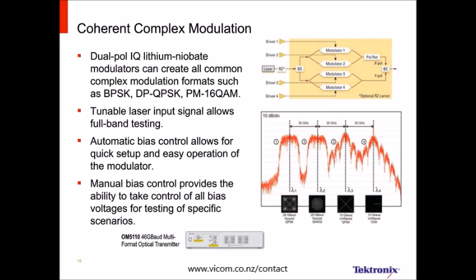But if you can spectrally shape this, that is, don't use a fast rise time square pulse, instead use a raised cosine type pulse, now you can get a square shaped spectrum, and so you can get a lot higher baud rate here. This is 28 gigabaud, and it fits into actually a narrower slot than the 10 gigabaud because of the spectral shaping. So just another example of how being able to craft arbitrary waveforms is increasingly important.